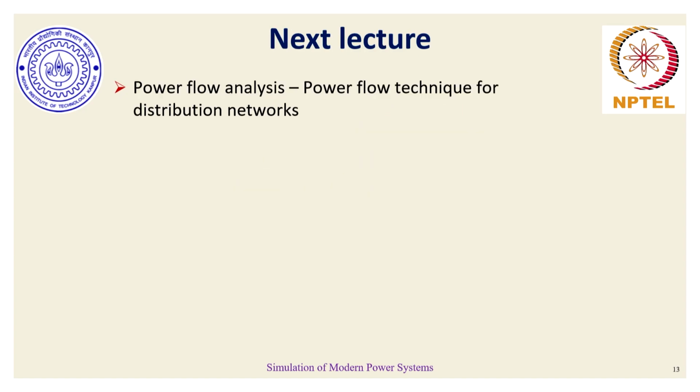So that's all for the DC power flow model. It's a very simple, linear, non-iterative technique. In fact, it has always perfect convergence as long as B dash is not a rank deficient matrix. And it helps the system operators get a quick assessment of what would be the impact on the network if at all the network experiences changes. Those changes are to be seen from the perspective of real power flows and voltage phase angles.